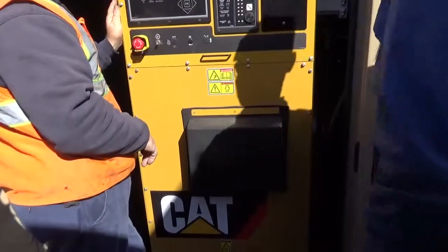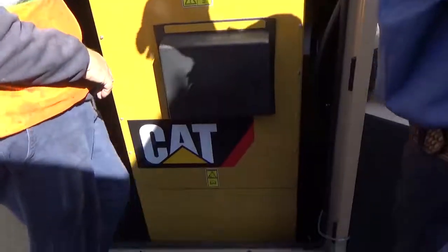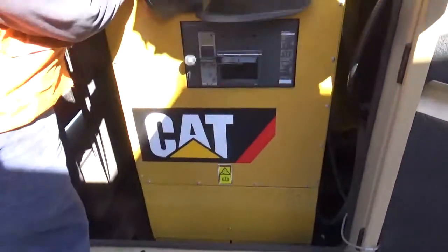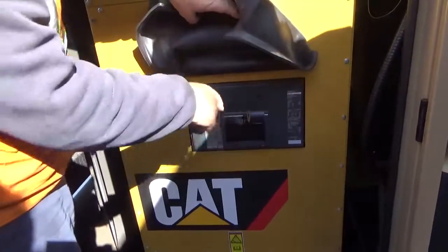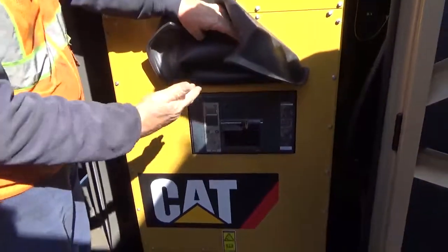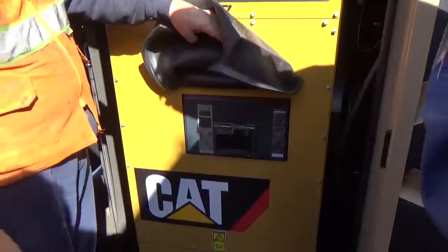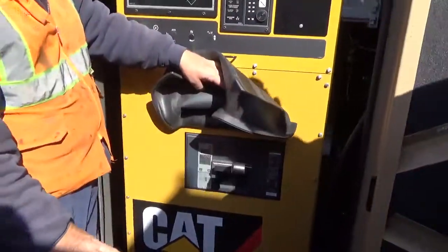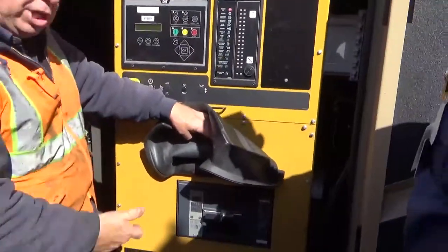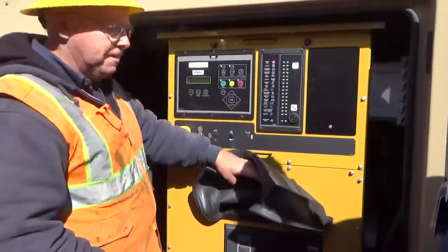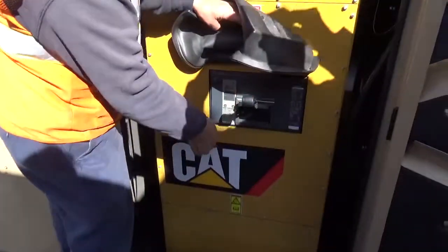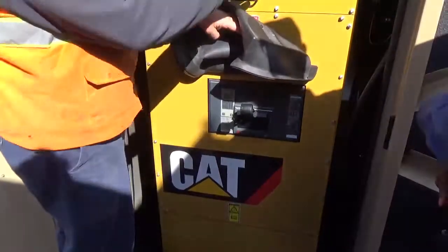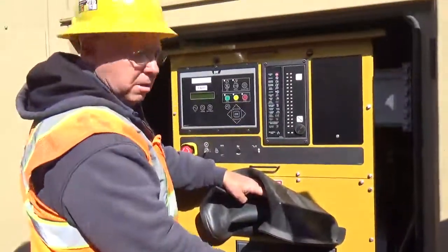Can you show the shunt trip again? What position is on and off and trip? Up is on, and trip is going to be in the middle. And then off is obviously down. And you have to go down first to reset it before you can go up. You just can't. Anytime this is in the middle, it has to go down to reset, clear the fault, and then you can go back up again.